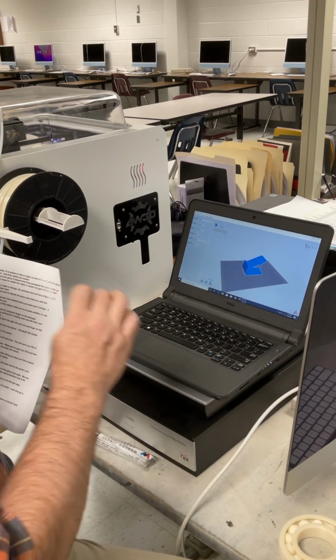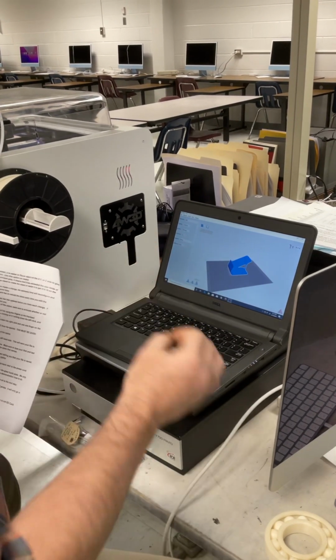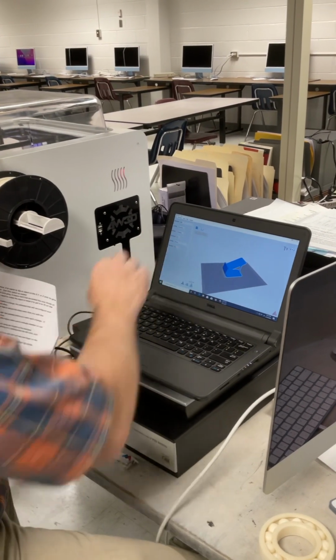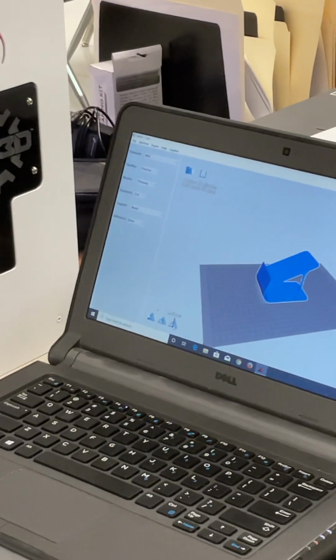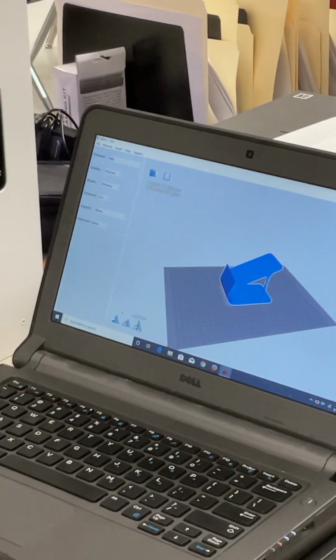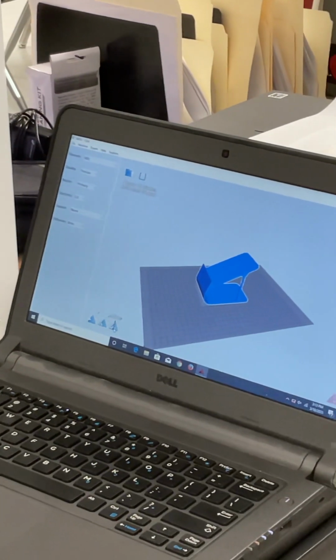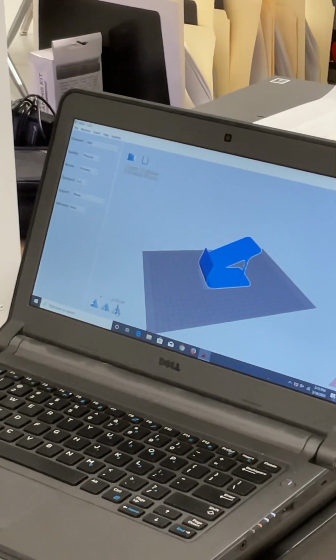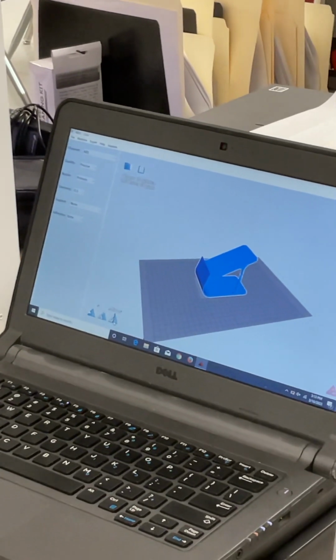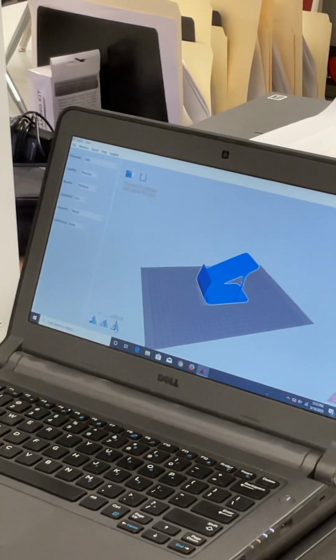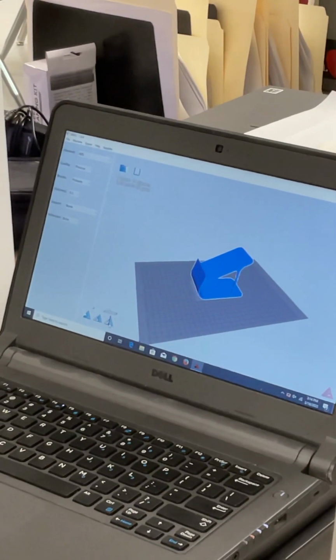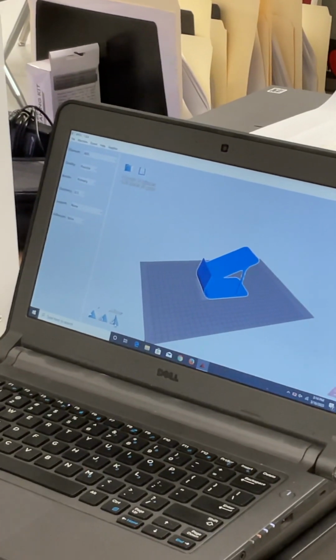And also make sure you notice, again, to reiterate, every time you make a change, that estimated time right there is going to reconfigure. And what it's doing, it has to rebuild the horizontal sliced layers, okay? Every time you make any type of change. So make sure you wait until that progress bar is updated before you make each change. It'll be a lot less frustrating for you, okay?